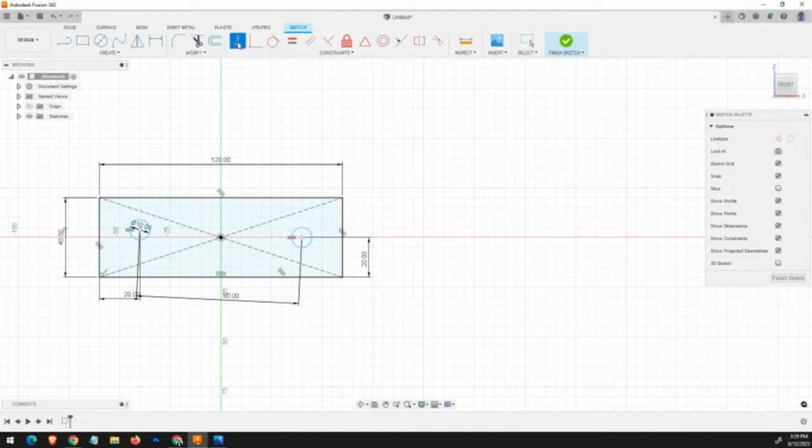So, click horty-verty. First click on this circle that is already fixed, and second click will be on this circle that can still move. Okay? Click. Alright, it's done. So it's fully constrained now, so there is no more blue. It means we can now proceed to doing it into 3D.